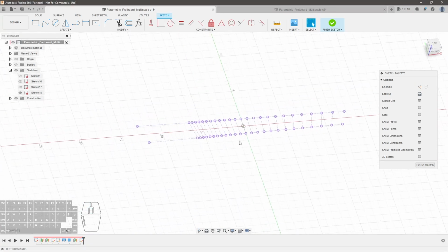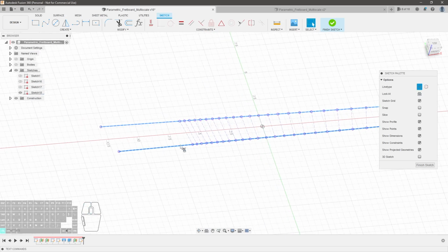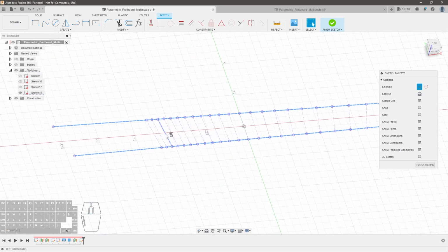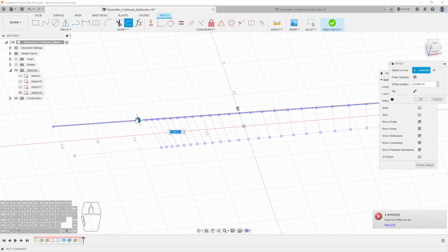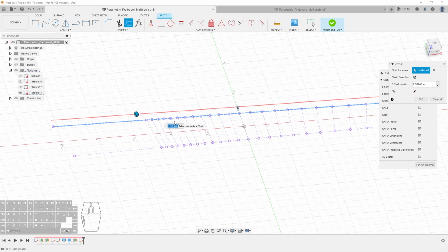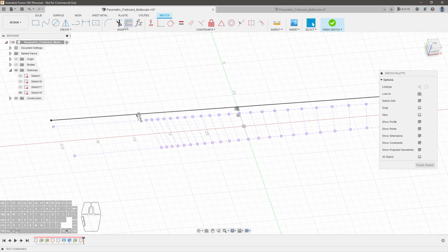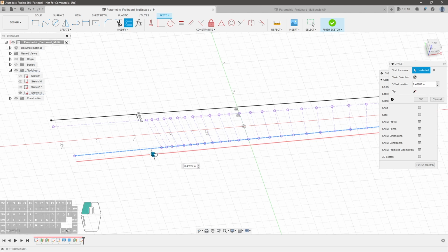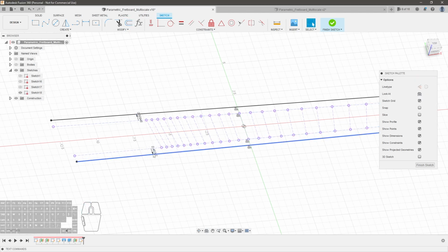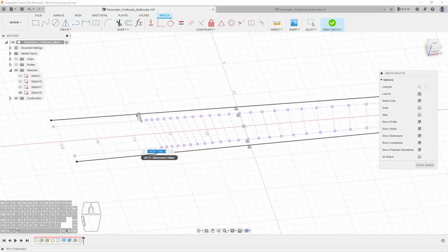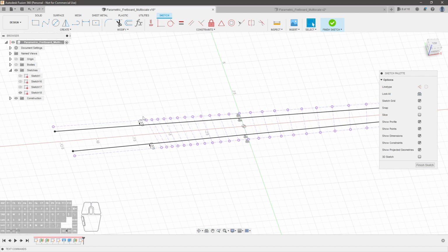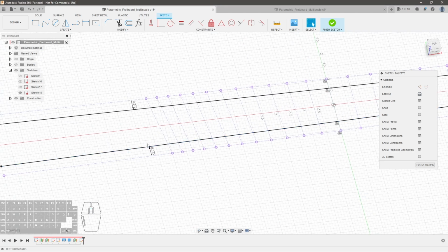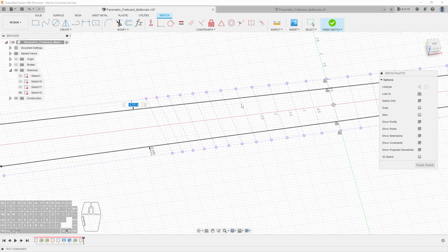And what we did in the previous video, we're going to do the same thing. We're going to go ahead and say offset. We're going to offset these 2 lines. So this one, and we're going to just hit enter for now. And then we'll do this one as well. Enter for now. And let's check these. These are both positive values. And if we drag it, let's do like negative 0.375. That goes to the inside, negative 0.375. Yes, that goes to the inside. So we're good there.